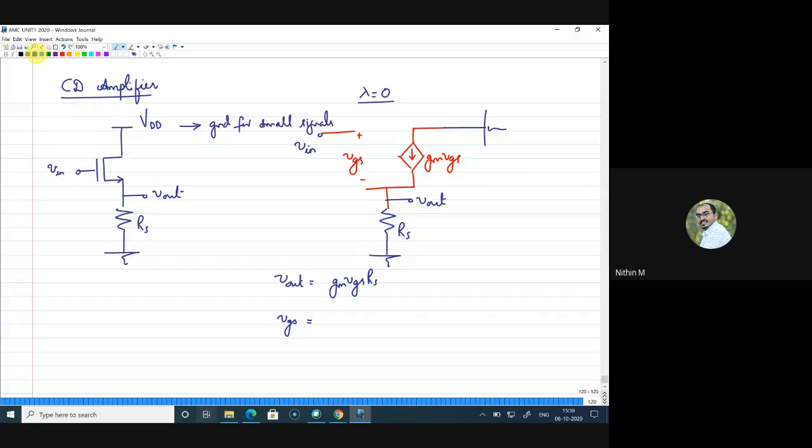All right. So to find VGS, previously in all the previous cases, in your common gate case or even in the previous cases, this did not come actually. So you may be confused. How you can get the relationship between VGS and V in is just write a KVL there. So it is V in. So from ground to this point is V in minus VGS. Then here is plus minus V out.